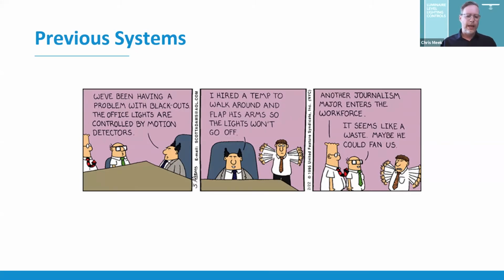And so one of the great things about LLLCs and LED lighting in general is that virtually all the transitions in light levels are really seamless due to smooth dimming capabilities, which operate essentially transparent to the occupant experience. So with LLLCs, when daylight is present or when occupancy is happening, you're going to get a smooth transition that's not jarring, that's not disruptive, and delivers a higher level of comfort to the occupants while still meeting all of the controls intent around daylighting and vacancy or high-end trim to deliver a great experience and meet the most aggressive energy savings goals.